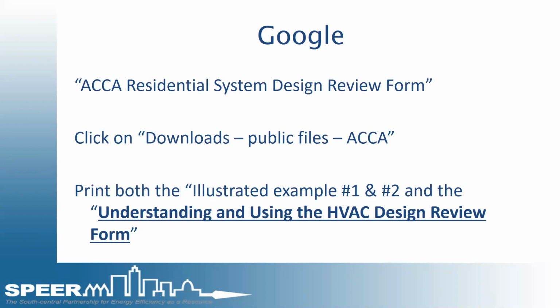Now, can an HVAC system cool a house with an undersized return, saggy leaking ducts? Yeah, as long as it's 2 tons oversized, which is kind of lots of folks' rule of thumb in Texas, which worked better 25 years ago than it does today. As our envelopes get better, our windows are better. All of the 2015 Energy Code is a pretty stringent envelope, so we really need to be utilizing this form at permit.